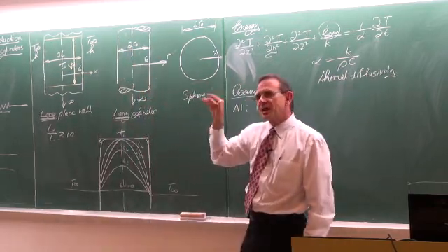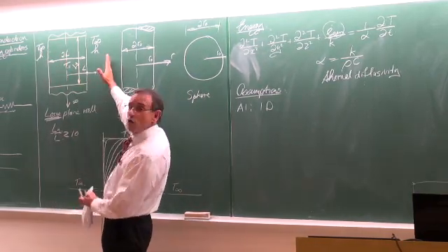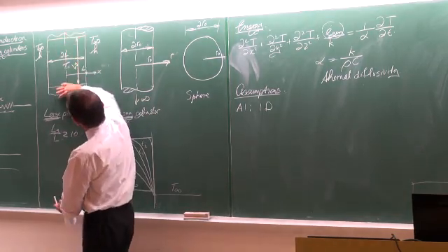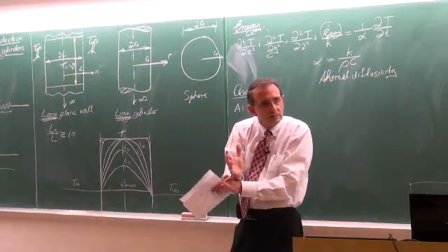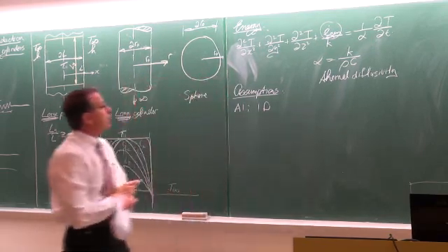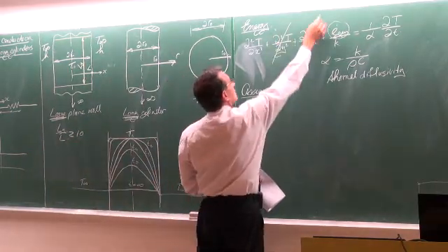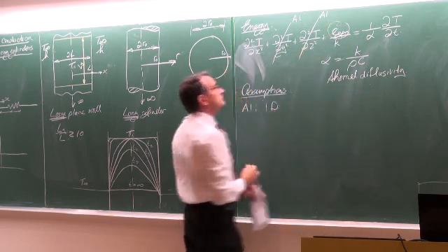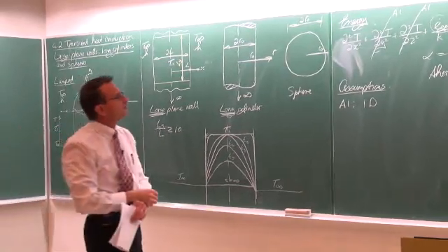So this category of problem is about the heat transfer moving only in this direction. If this thing is very, very large, then what happens at the ends is negligible in terms of the total picture. So we are looking at a one-dimensional problem. If the assumption is one-dimensional and we look at the energy equation, then we can say that that term and that term is equal to 0 because of assumption 1. It's a one-dimensional problem in terms of the heat transfer.